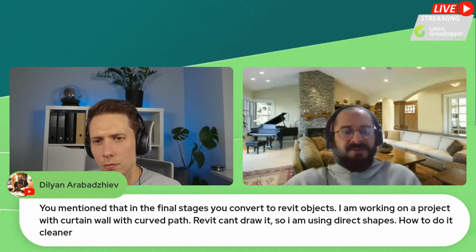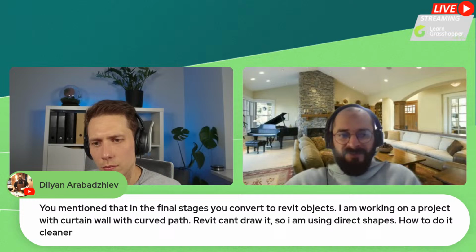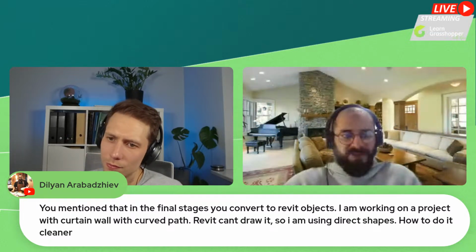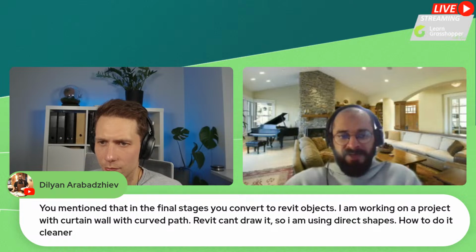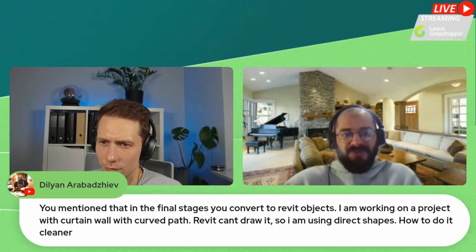I think there are some native objects for the walls. If you go to the architectural component, you will see those wall components. You can create those walls based on the line, or maybe based on the area, or maybe the height. Or the other way is, if you are creating a direct shape element, you can use a generic template, and you can push this geometry as a family through that template.